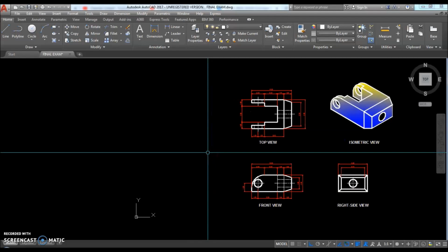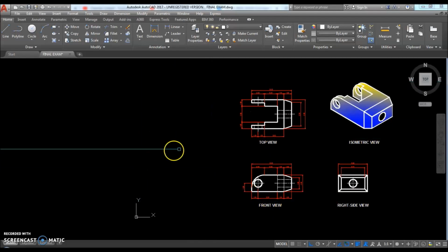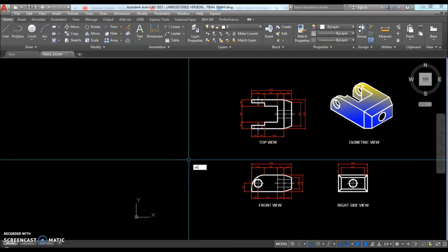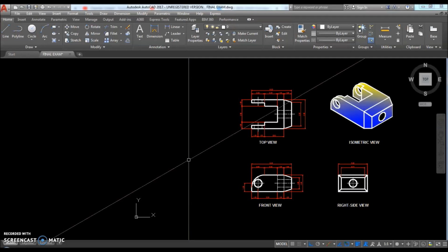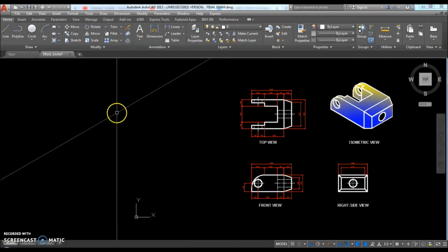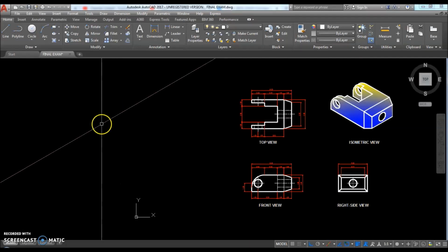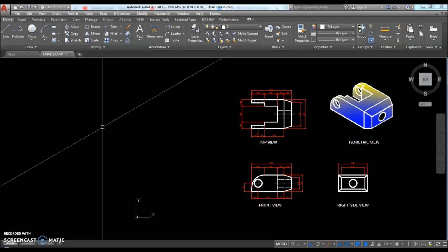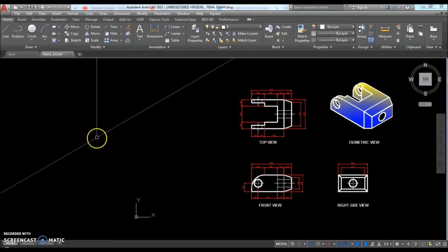To draw an isometric view in a 2D plane, you just type the command SNAP, then STYLE, and you will be asked to enter a new value. The value for isometric view drawing is 1. Enter. And as you can see, our crosshair automatically changed to drawing isometric lines.